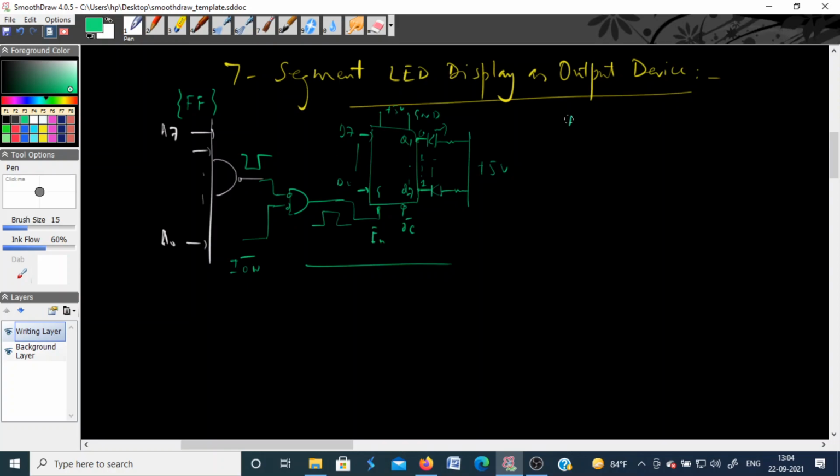So you can load the accumulator with any data. Suppose I write MVI A, 01H, it will load the accumulator with the 8-bit number 01, that is 00000001. Once you have loaded the accumulator with this data, you can move it to an output port.